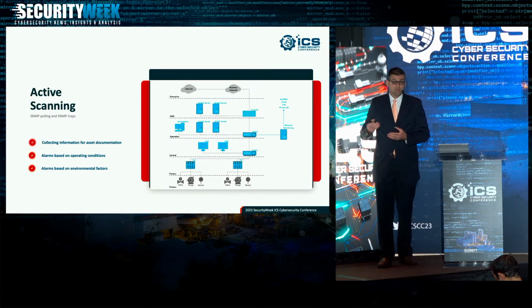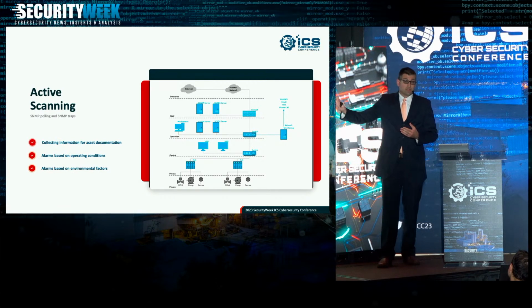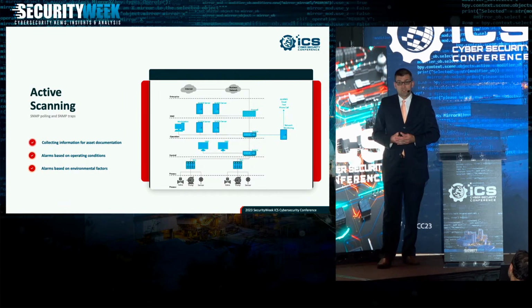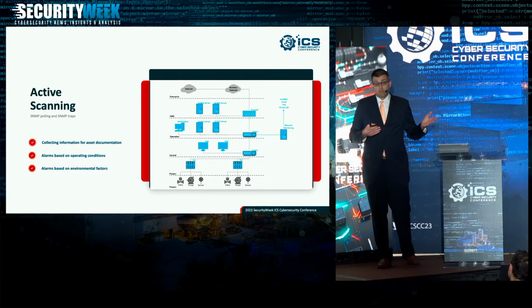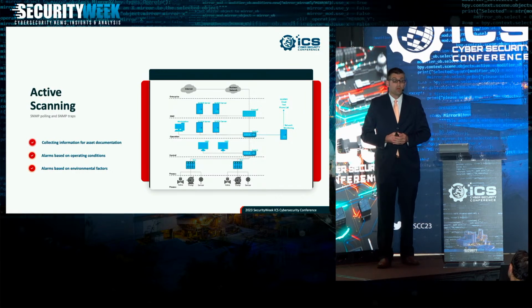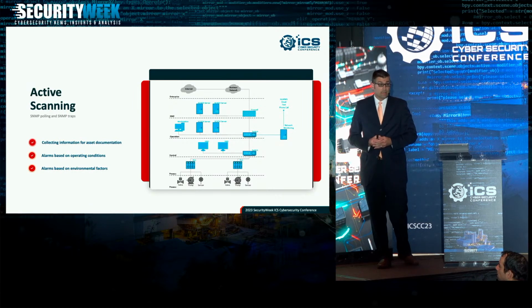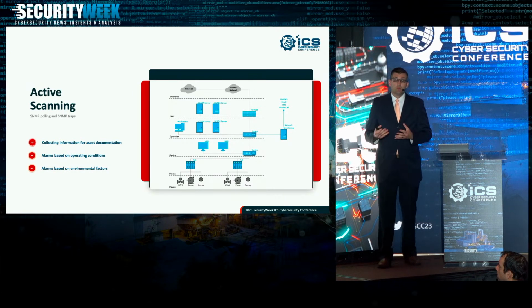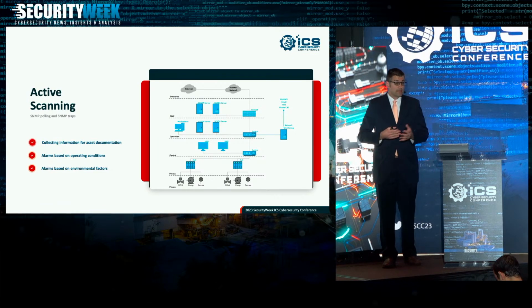Are there other times where the bandwidth and the processor are spiking and we're seeing high utilization, especially on our edge devices? If we see the processor spiking on our firewall, is it externally a denial of service attack that's trying to hit? Or if it's on the internal port, is somebody trying to move large amounts of data off of the OT network? These are things, again, we wanted to be aware of, to be able to respond to and investigate.